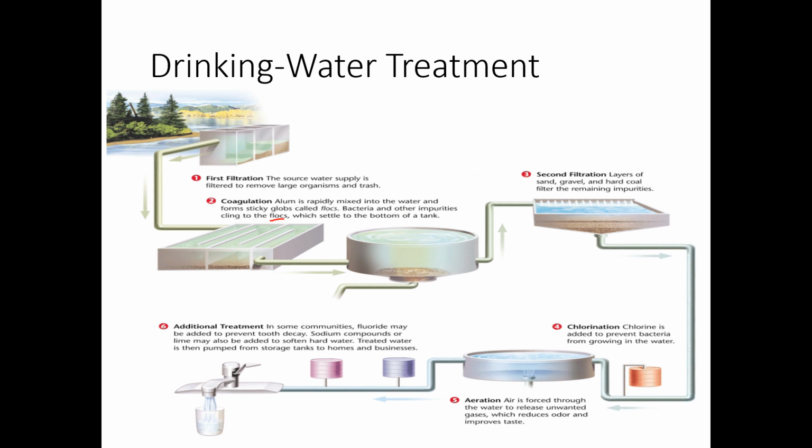And then finally, or second to last, you're going to have aeration. Aeration is more of a cosmetic thing, something we do to help make our water smell a little better and improve the taste. When you add air down here, it helps to release other gases in the water that cause a bad smelling odor or make the water taste really bad.